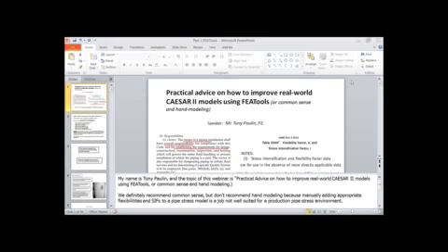Right. Well, the short answer is that it definitely did have slotted holes, and that's a great question. The reason that it bowed was because it was an LNG catch tank. So it had LNG that would collect in the bottom of it, so it would freeze. The bottom would contract and the top would stay ambient, and that would produce the bowing. So the vessel literally bowed. We modeled the bowing in that vessel with Caesar.